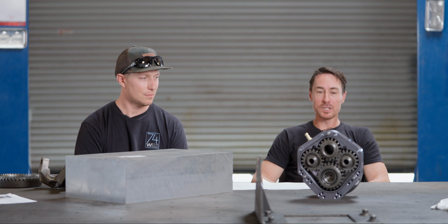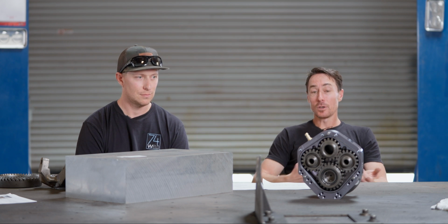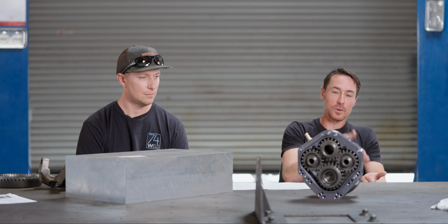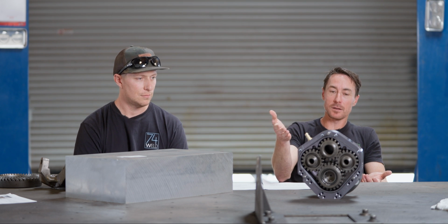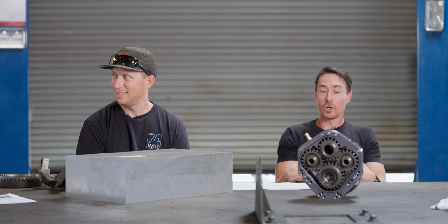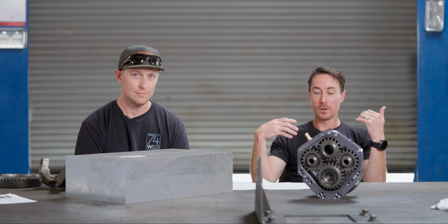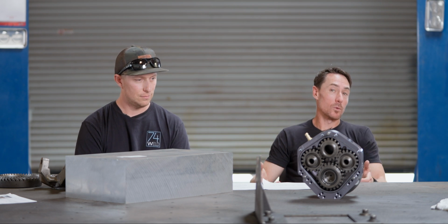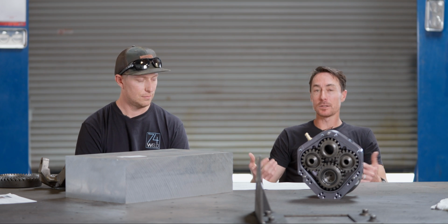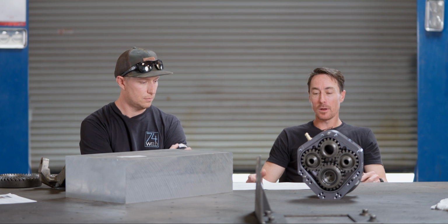It's just a piece of equipment, but if you want to keep your equipment nice, and you guys do care about nice quality equipment, because if you have a machine that is clapped out and so much ductile iron has gone through the ways that now the ways are loosened up, now you have a machine that doesn't really want to hold tight tolerance, the implication of that is parts that are not really made to spec.